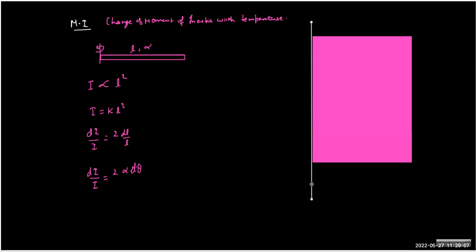During extreme summer, if you don't leave a gap between the wall, it is a very common problem that in the afternoon the gate gets locked. Because of the expansion, it will push the wall and touch the wall, and therefore it is difficult to open and close. You might not have faced this issue, but I have faced this issue a lot in summer in my hometown, because the gate is so large that the expansion is significant.